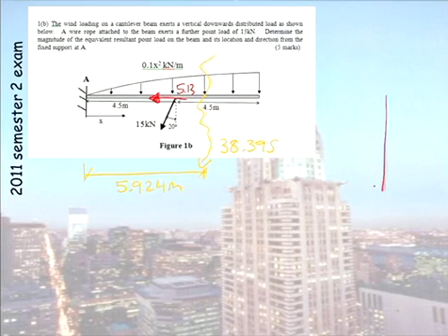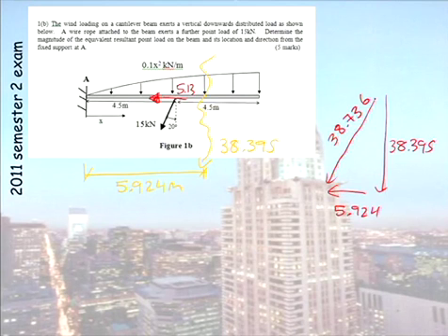And then our final resultant here, using Pythagoras, would work out to be 38. And again, using trig, you can work out that angle in there is 7.61 degrees. So that would be as complicated as a Part B question would get. The easy ones would just give you that linear varying load and ask you to work out one resultant. In this case here, you had a linear varying and a point load, and the point load was at an angle.